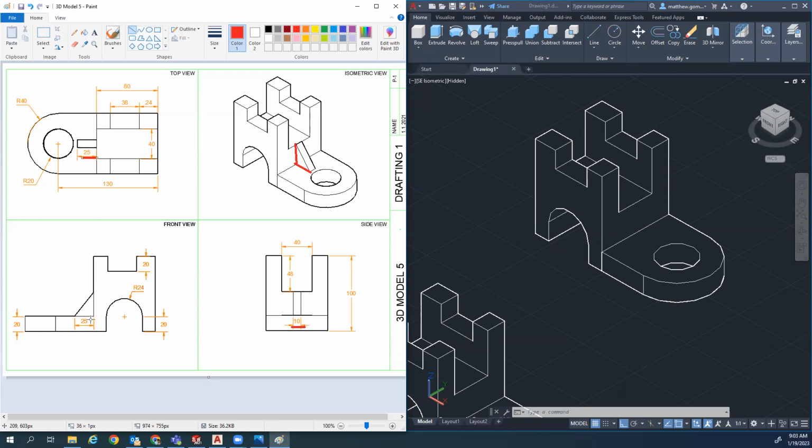And then there's nothing mentioning how tall the triangle is anywhere, but it goes from this ridge to this ridge. So if I were to just draw a line from here going straight up, I can see that it's 32. So that's how tall my triangle needs to be. So here's my measurement here. Let me write, it's 32. Oh, that's a line tool. So it's 32 tall and it's 25 that way, connected, and then press pulled back 10.